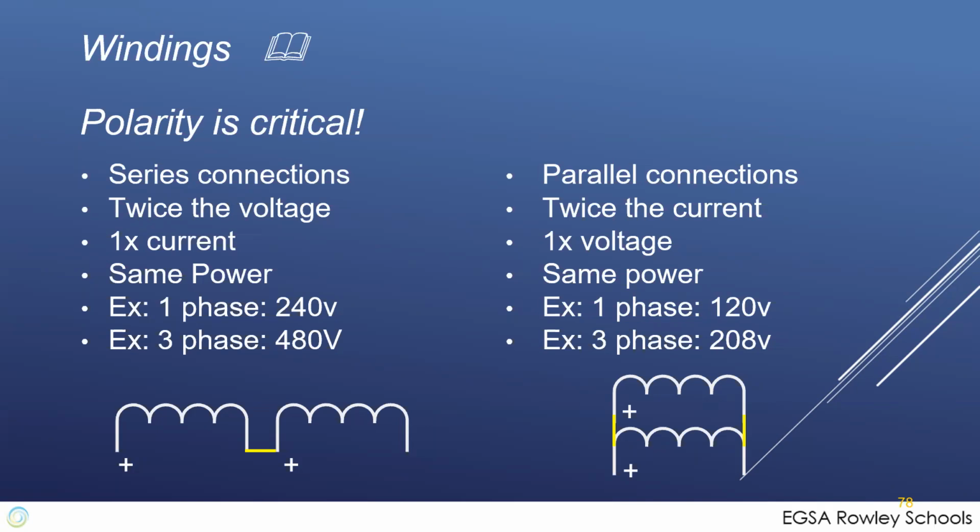One of the tests we did when we were doing our new winders was actually to cut the leads off and say, okay, figure out which winding goes on what machine. And you can do it with a voltmeter and a battery. You can flash and bump them, and you can figure out which winding pairs are there. So it's possible to figure out a machine where all the markings are cut off the end of the wires. You can still, with an ohm meter and a battery, figure out which one goes where.